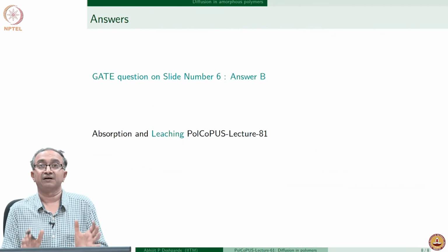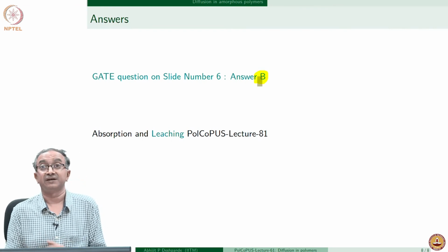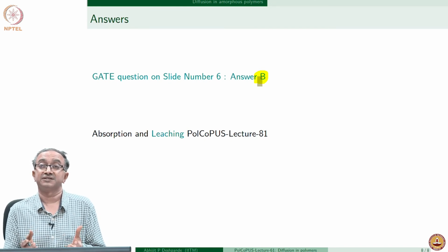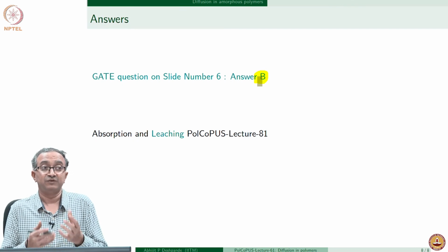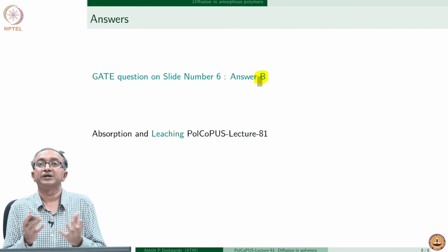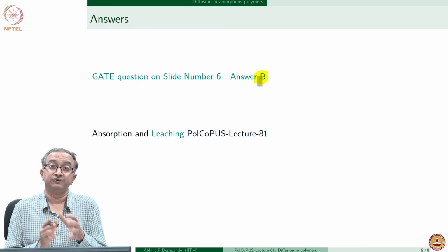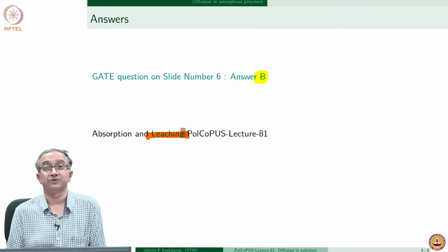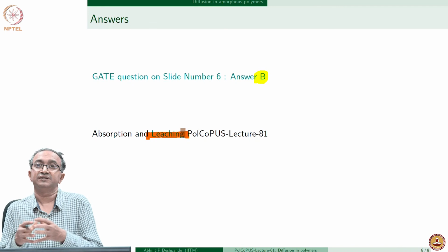With this picture, I hope you can see that because of the plasticizer coming out into the organic solvent, the glass transition temperature will increase, and because of that, the material which was in the rubbery state will now become more glassy, and therefore it becomes rigid. And in this, not only is diffusion happening, but the overall important phenomenon of leaching is also happening. Leaching is a process by which a small molecule goes from a solid state to a liquid state.